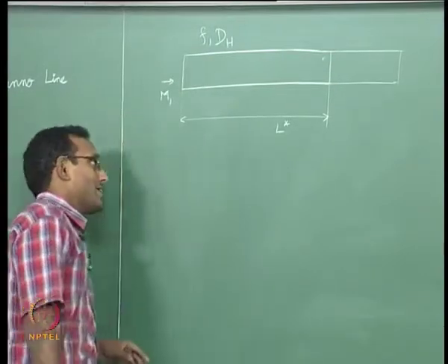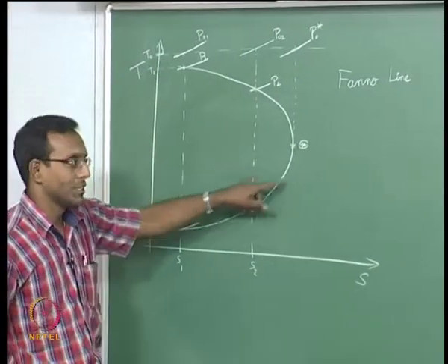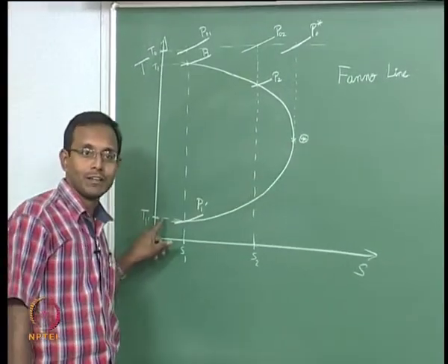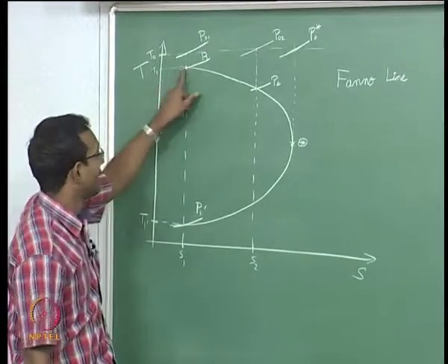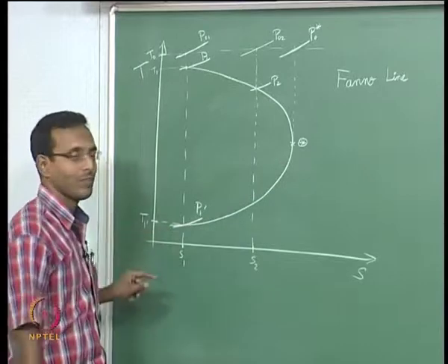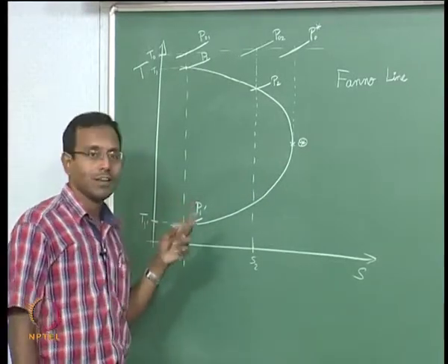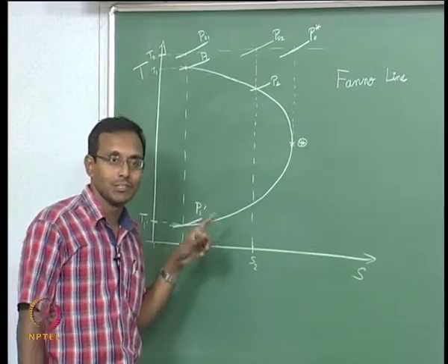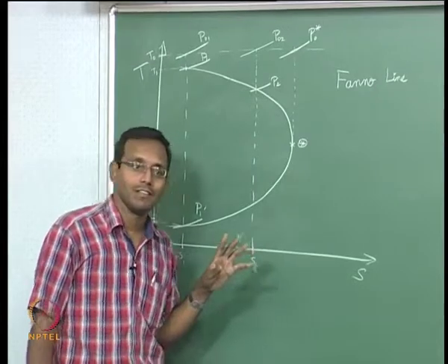If I go back and look at my curve here, this curve comes from all those expressions we have written till now today. Okay, whatever we wrote today as the integrated expressions will finally give you this particular curve for Fano line. The change in m dot will never be given by this solution, because during the solution we assumed that m dot is constant, okay.